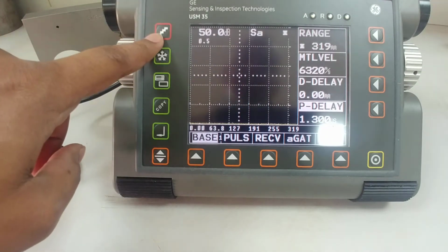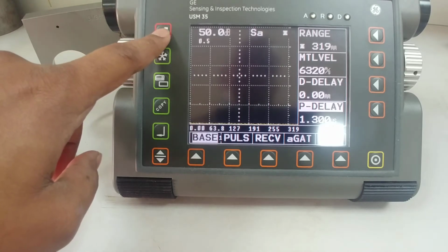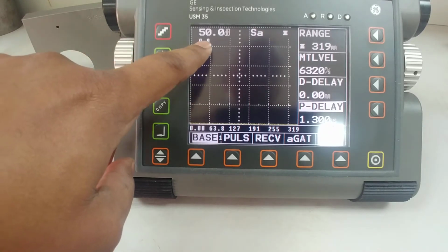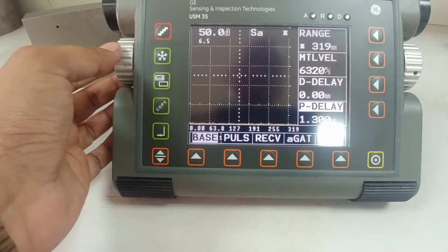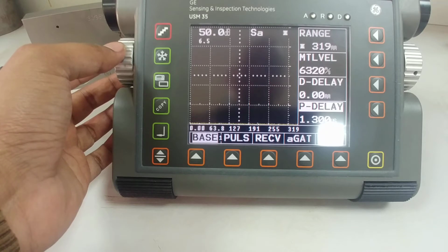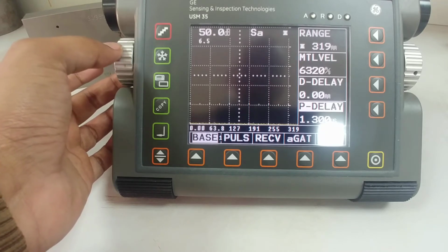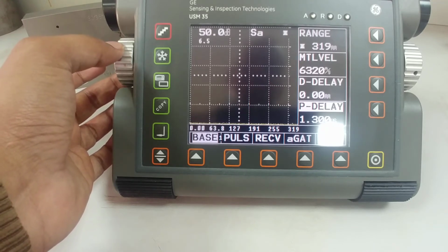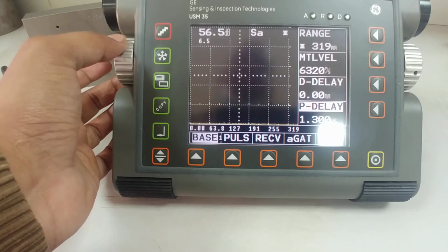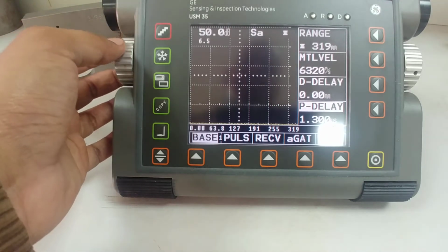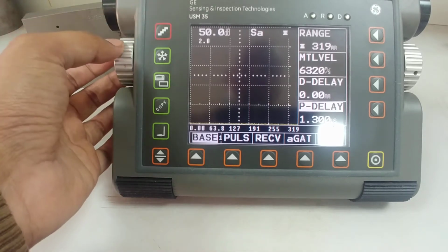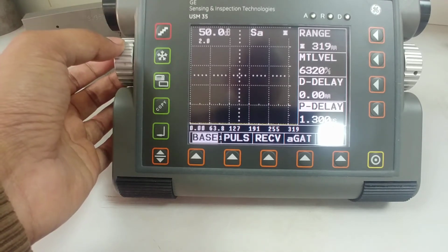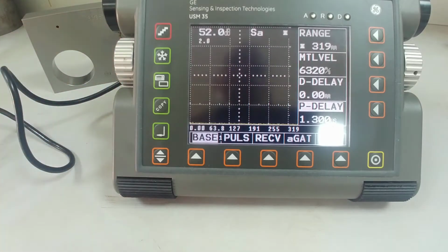So this is the step button. If I press the step button, this gain incremental value will increase or decrease. So 6.5. If I just rotate this knob just for a small bit, the gain will increase by 6.5. You can see. Same way, if I reduce the step size, something like 2, if I increase the knob one time, you can see it's increasing the gain value by 2.